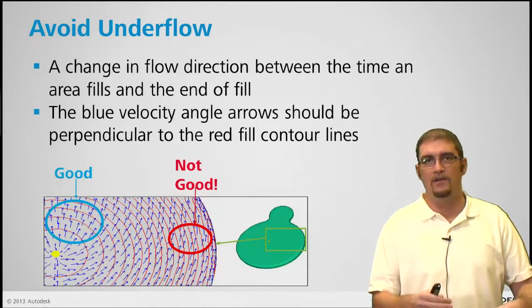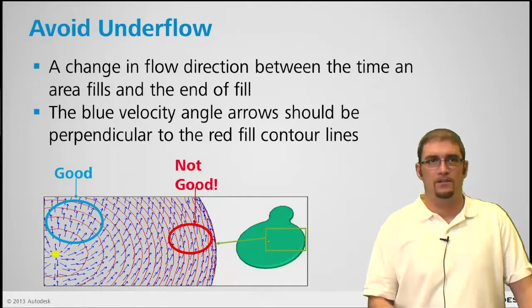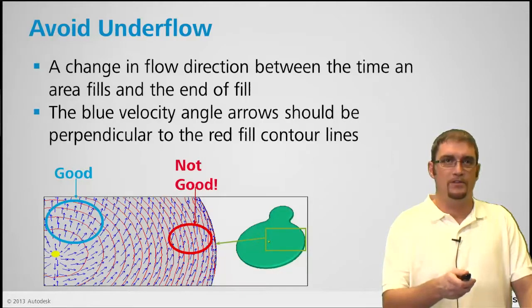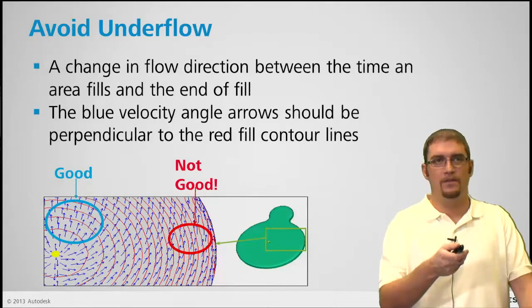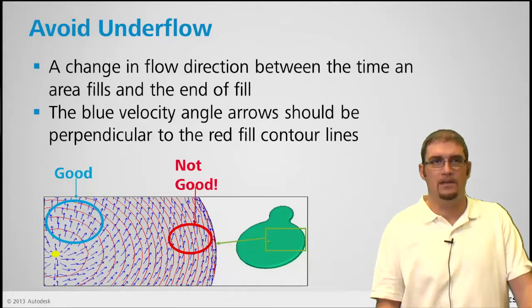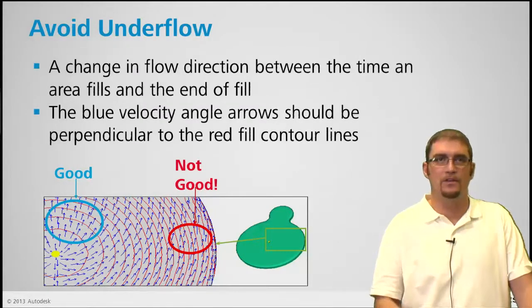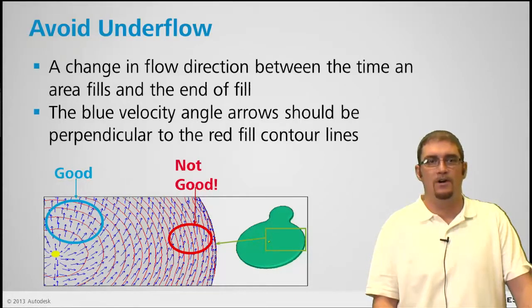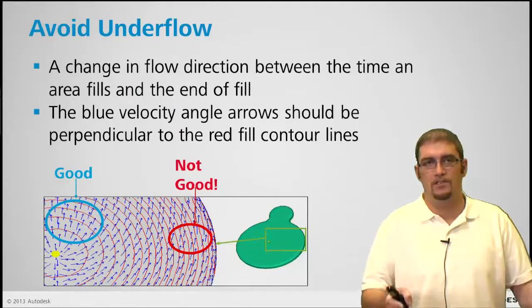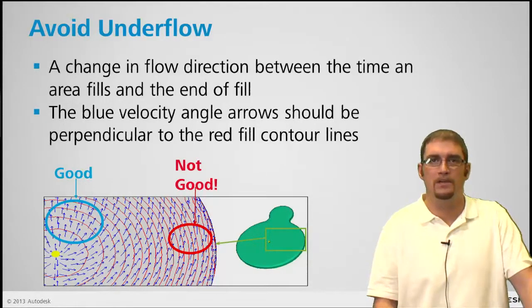So you have quite a bit of mix in orientation, and you can see here the blue is good, and you can see our fill pattern, contoured lines overlaid with the orientation, and you see our perpendicular, that's good. If you start seeing something that's starting to run parallel, that's not good, because it's shifting up towards that tab in this case. So be careful of that.